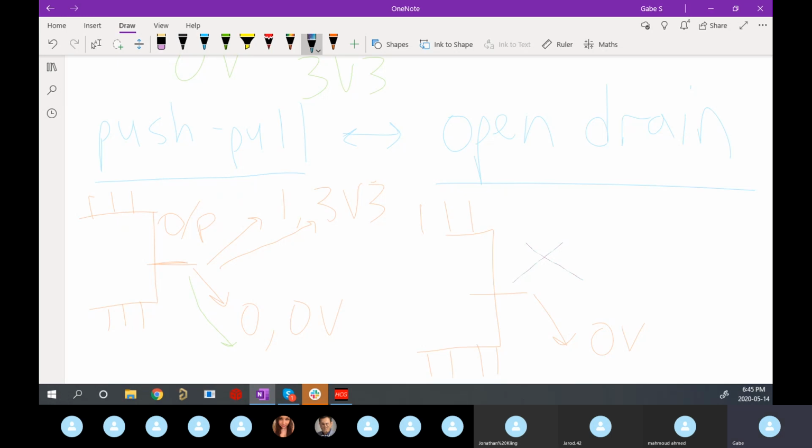which seems counterintuitive, right? We were talking about making sure our pin is defined in every state, especially for inputs, reading signals, and for outputs, we want it to be defined as well. Open drain is kind of a weird state, and it's useful in a couple of different scenarios. It's pretty rare that we want to leave it floating.